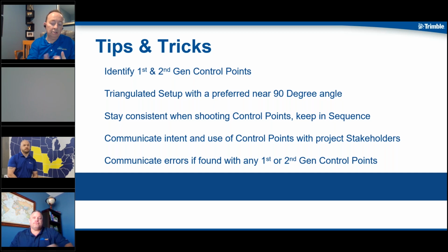Again, we talked about those being the civil control points versus the building construction points, okay, building control points. But what we want to always try to do, as we migrate over and start getting inside that building, is incorporate one or two, if we can, of our original civil control points so that we stay grounded and we're staying on that grid that we've got associated on that job site. So keep in mind about that.